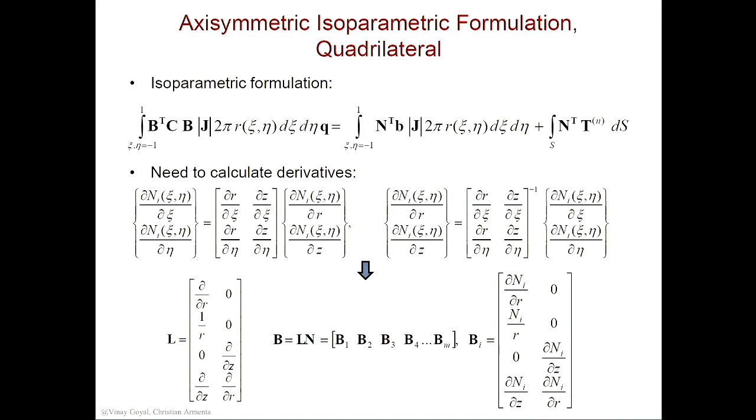Remember that if I have these calculations, these numbers, don't you agree that, for example, for shape function 1, which is this block here, the derivative of N1 with respect to r can be calculated now because I have the Jacobian? I have these two calculated. If I know N as a function of xi and I have N as a function of eta, I know these numbers. I know the Jacobian. Then I can do this calculation to get these components, which can be filled out here for each of these blocks, okay?